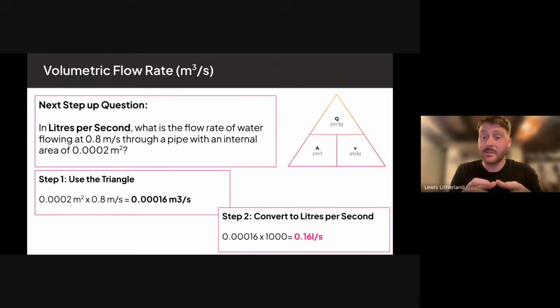That's as simple as we can make this, and that's as simple as we need to go with this. 1 cubic meter holds 1,000 liters of water. So you just have to convert by multiplying by 1,000. If you go the other way, obviously divide by 1,000. There are lots of questions in this module relating to this, and all it is is understanding that. So liters per second to meters cubed per second is the other way around. Again, the key number here is 1,000. If you're not fully aware of that, I'd probably write that down somewhere, just how you're going to convert this. Okay, nice.